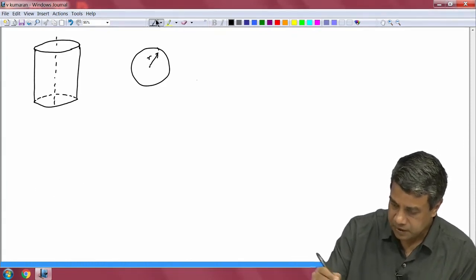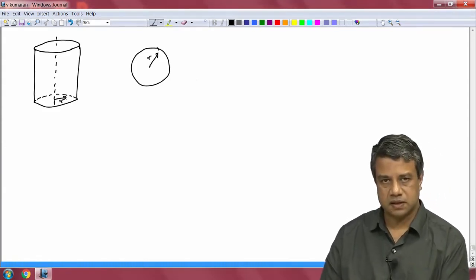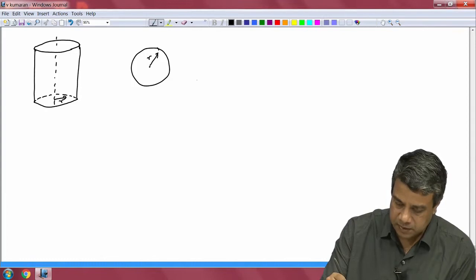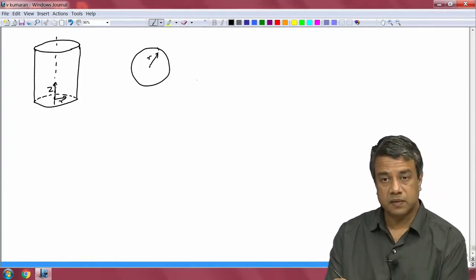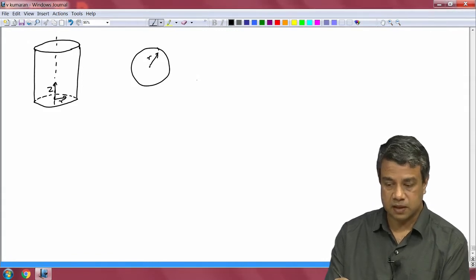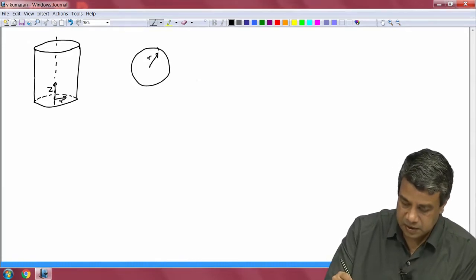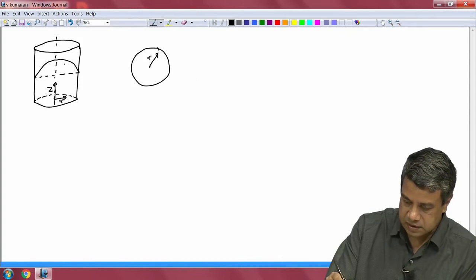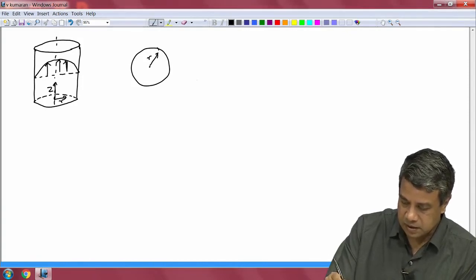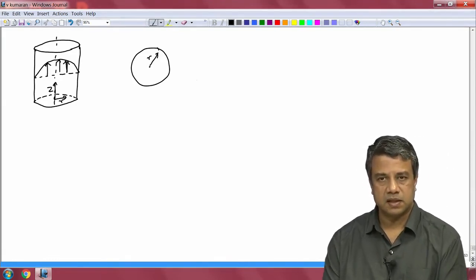So, the first one is, r is horizontal in this left figure. The perpendicular direction is z. So, one could for example consider the transport of z momentum in the r direction, because that is perpendicular to r. In that case one would for example get a velocity profile that looks something like this. The transport of z momentum in the r direction, and write a balance equation for that.